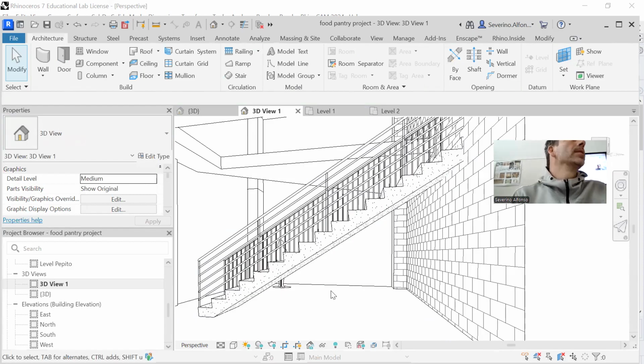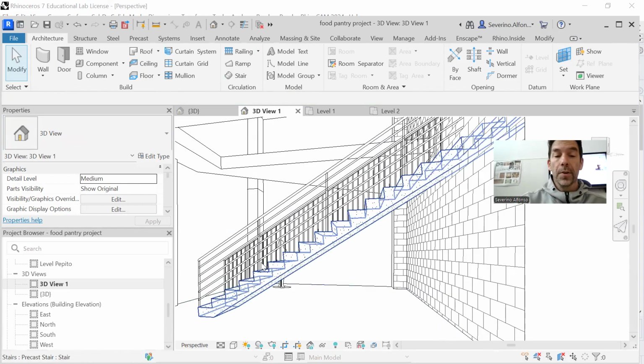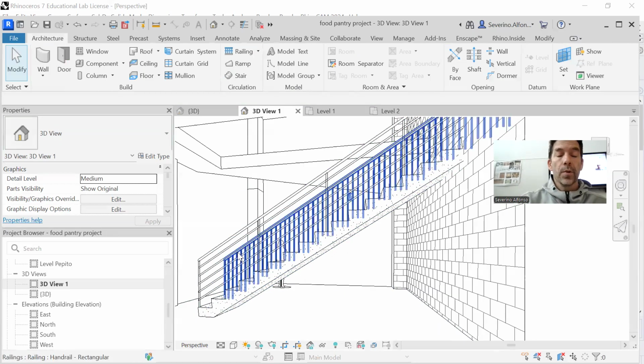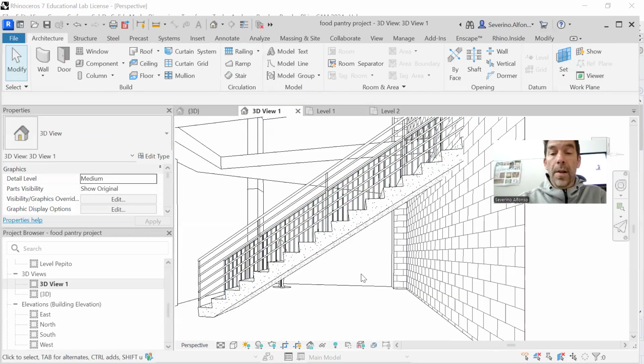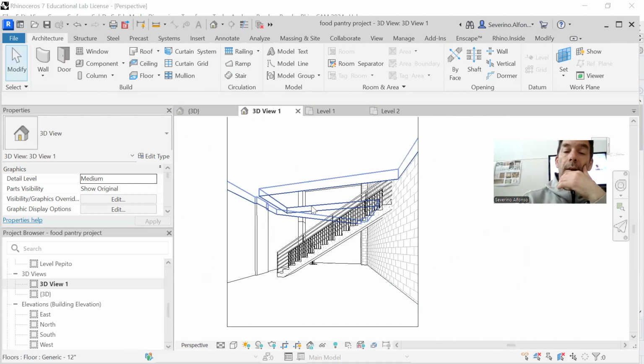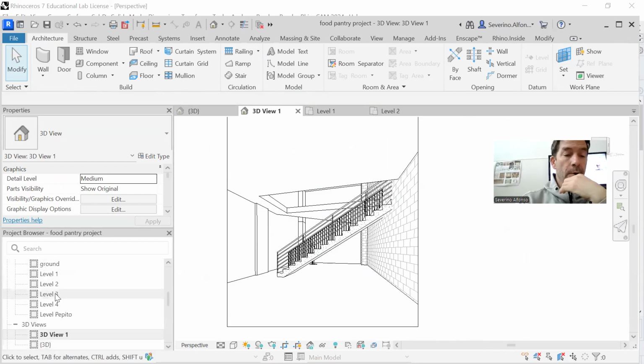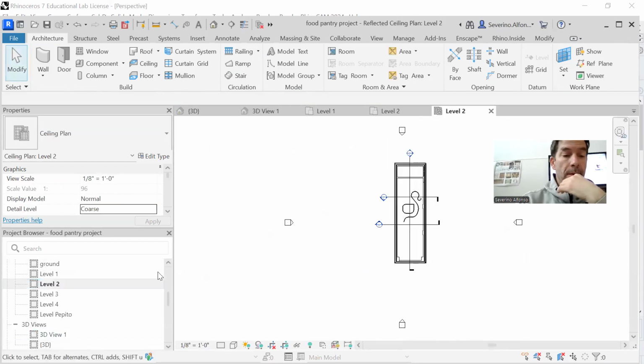Beyond that, if you want to be specific, that's when problems come, because Revit has the standards. And maybe you can download some other families from the web, but that's the lack of creativity maybe where Revit doesn't serve as well. There are two railings, you can change each of them. You can also eliminate the railing, it's just deleting it. Railings are automatically assigned to stairs. You can create your own railing, whatever level.